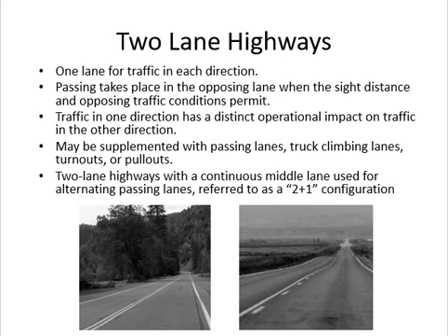You're not climbing on the truck. Okay, nobody is climbing on the truck. The truck is climbing on the gradient. Okay, so you have a gradient going up. Now you know if the truck is going in your lane on this gradient, it will go slowly. Okay, the cars can go faster. So you give an extra space to the truck so they can go into that lane until they pass the gradient and the cars will move faster. Okay, so climbing lane is for that, and passing lane, you know, passing lane, so to make the passing safer.